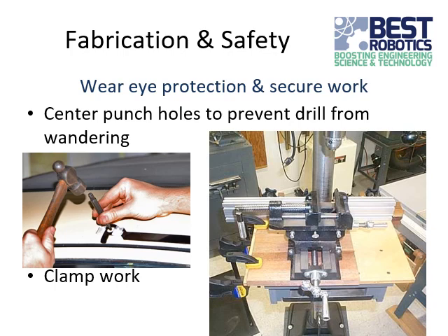You don't want to sit there and hammer it with multiple hits, because it can bounce around and make multiple holes, which kind of defeats the purpose, because then the drill can go from one hole to another, and the whole point of this is to keep the drill from moving. So, yeah, and then clamping your work is always a good idea.